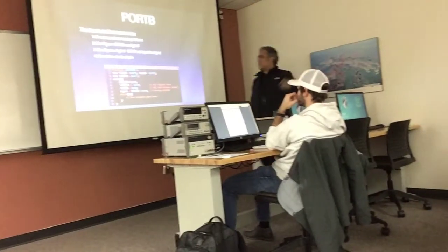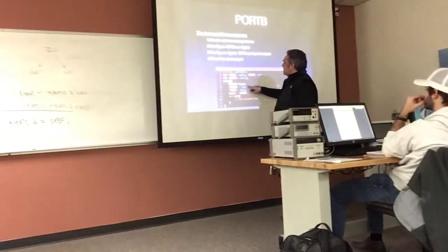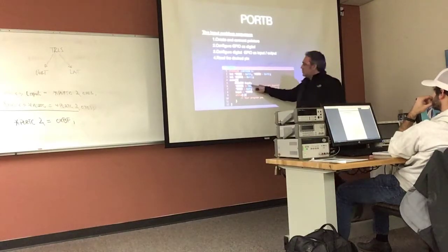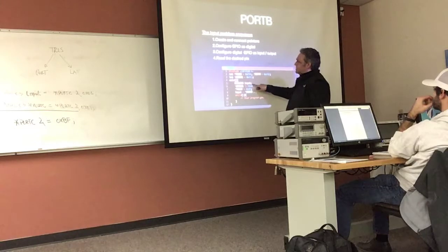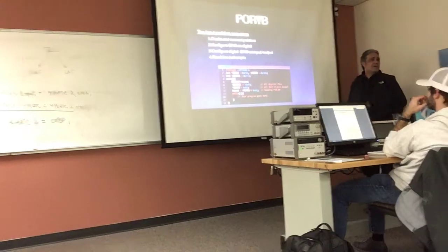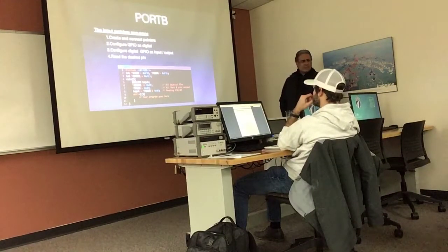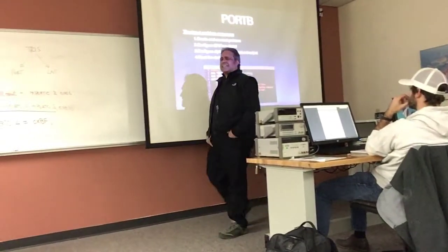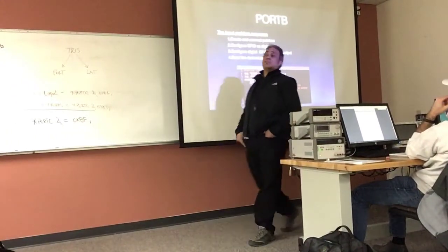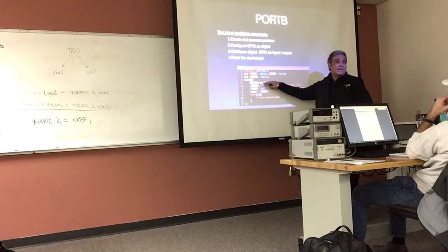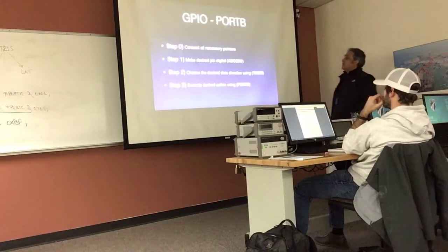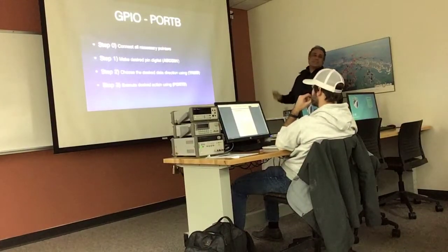One thing that you have to remember is this. This compiler in particular, or most of the low-end compilers, will force you to create your variables right there at the top. If you don't, it gives you an error, I think it reads like "expected identifier at this spot" or something like that. It only means make sure that you declare all your variables on the first line. Don't do it after you begin executing, or the compiler will just bark at you. Okay, so that's the recipe, exactly the same as port B.